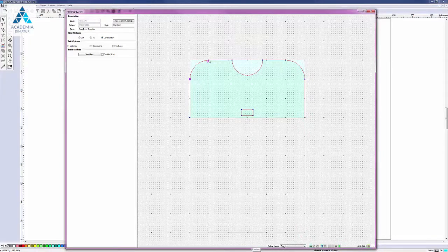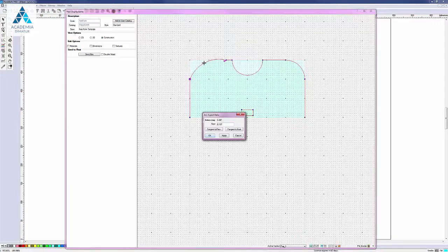Now if I was to drag this point somewhere else, say so we're saying drag point is G, I'll drag it over here, and now we see that the curve is no longer tangent at this point. It's not tangent to the straight part. So if I go back in here and so this is the curve, as here it is, at line, curve line, and I say period and say tangent next, now I'll get a line which is tangent to this little straight bit, and pressing tangent previous I get something quite different.